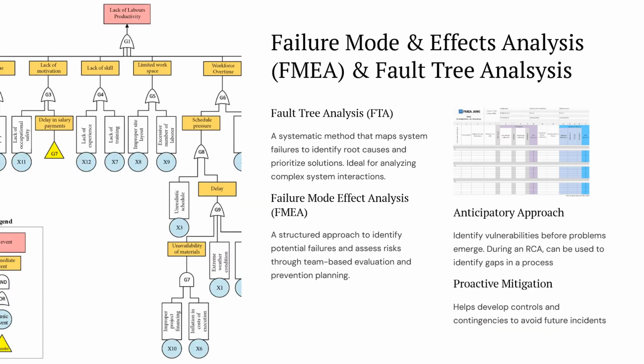A couple other tools that can be used are your failure mode and effects analysis and the fault tree analysis. Now these are more proactive mitigation tools that help develop controls and contingencies to avoid incidents before they occur or future incidents after one has occurred.